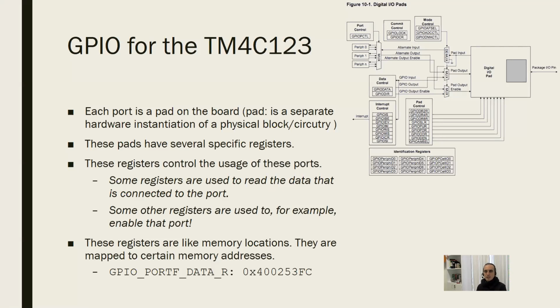I mean, any device we want to control will have function registers, control registers, and we are going to map our address values to those control registers. By writing to those addresses, we'll be accessing those registers and we'll be controlling the device. This is called memory mapped I/O. Okay.